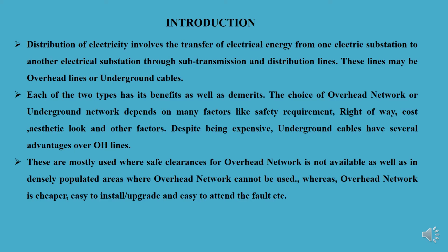Suppose it is a very congested area, a dense area, right? So an overhead network is not possible. At that time we have to consider the underground cables, right? So there are some factors, or some conditions, and according to that you have to decide the overhead network or underground network. Cost is also very important.